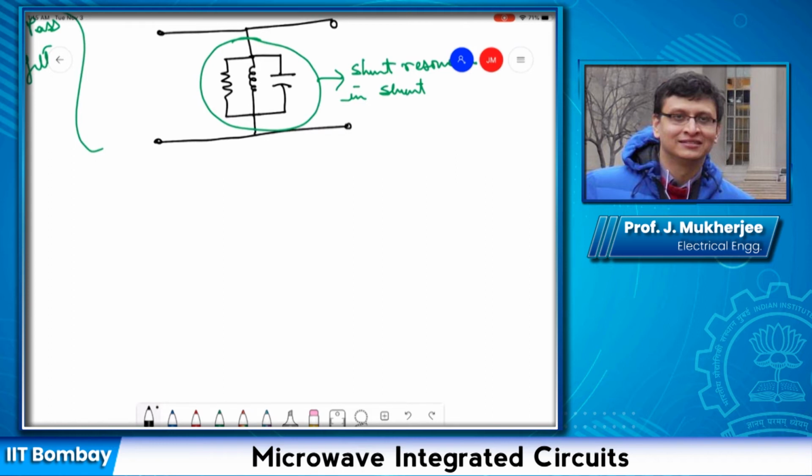Let us go back to this parameter S21 square, which we recall was used while I was discussing amplifiers. And I told that time that if the input and outputs are matched, then this quantity represents the total gain. Now, filters that we are discussing in this lecture are the passive type. If it is passive, then S21 square will be lesser or equal to 1.